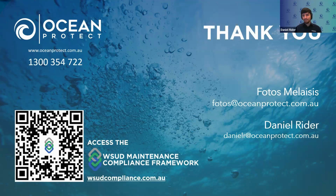Jun Bong asks, maybe out of today's topic, is WSUD best practice compliance required if stormwater is proposed to be discharging to a surrounding groundwater or infiltration via a soakage system? So long story short, do you think you need stormwater treatment if it's just draining to an underground aquifer or groundwater? Any comments on that? Yeah, I'd definitely say yes. But it's also subject to local jurisdiction or local government authorities' policies that are in place.